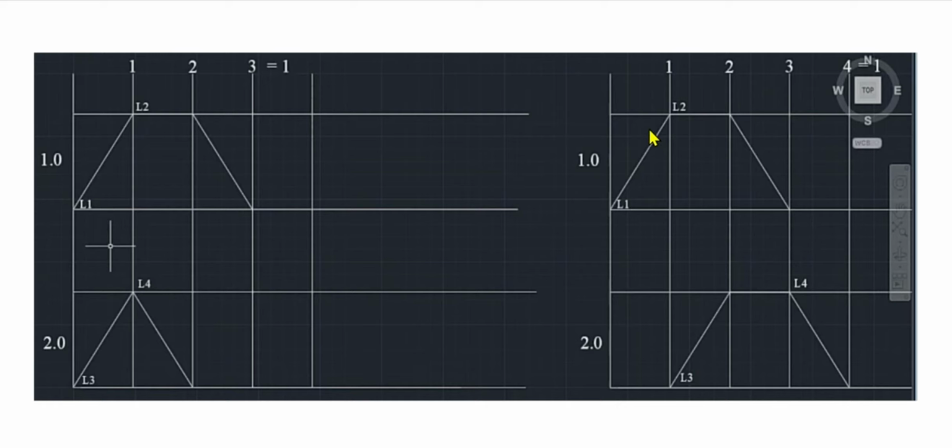Okay, so this will be continuous, since our motion diagram setup is continuous. Okay, so the last limit switch that will trigger the sequence will be L3. Okay, so this will be L3, and again it will start and then it will finish again with L3, and then it will start again the sequence.